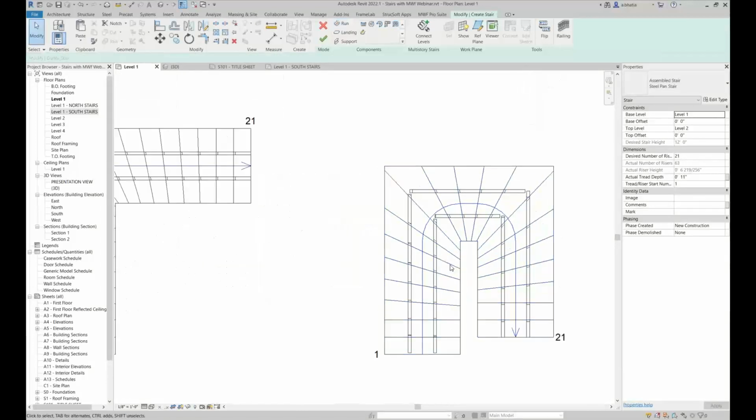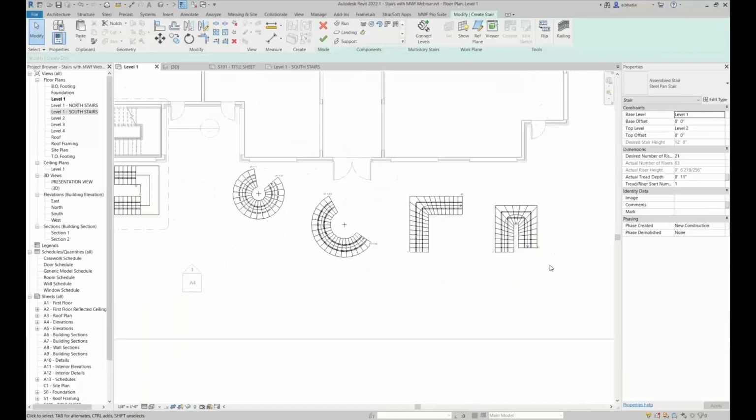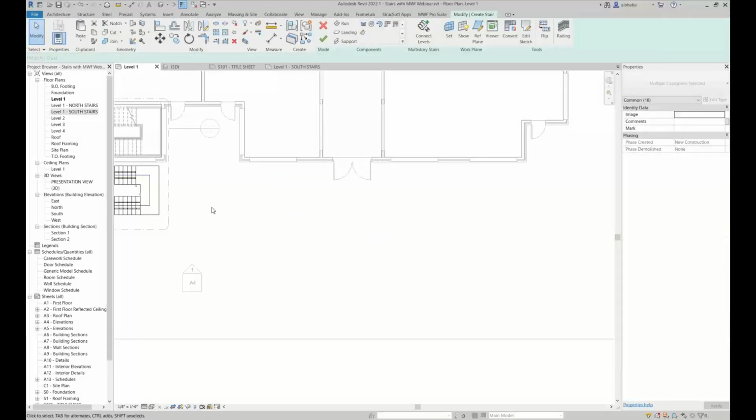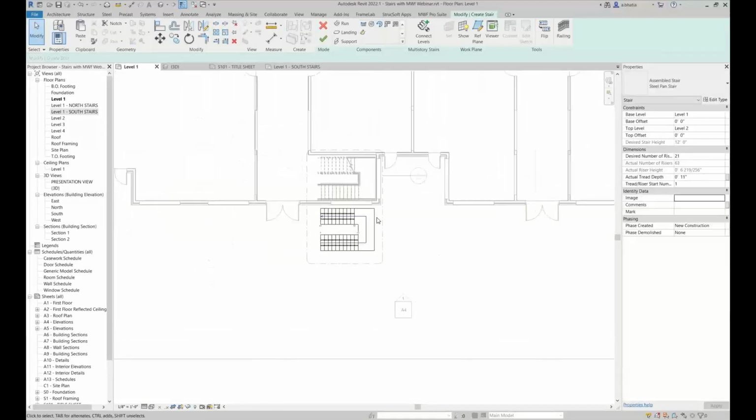So now if I draw a winder U-shaped stair, it's doing the same thing. It's preparing for the turn, and at the turn, it's creating these diagonal or triangular steps. And basically, the reason this is mostly used for residential is because for most commercial places by code, you need a landing because you can't expect people to just keep running up the stairs as they go along. You need a rest place.